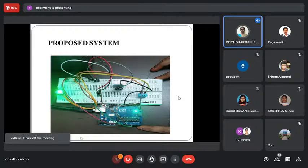So we are using the HC05 Bluetooth module, and it has 6 pins. Here TX and RX are the main ones for transmitting serial data as well as receiving serial data from the Bluetooth module. TX is connected to D10 of the Arduino UNO, and RX is connected to D9. DHT11 is for measuring the humidity as well as the room temperature. The data pin is connected to D7 of the Arduino UNO. This is the proposed system we have established.